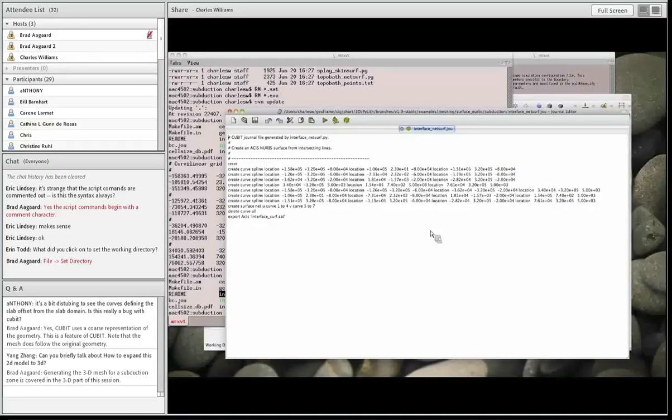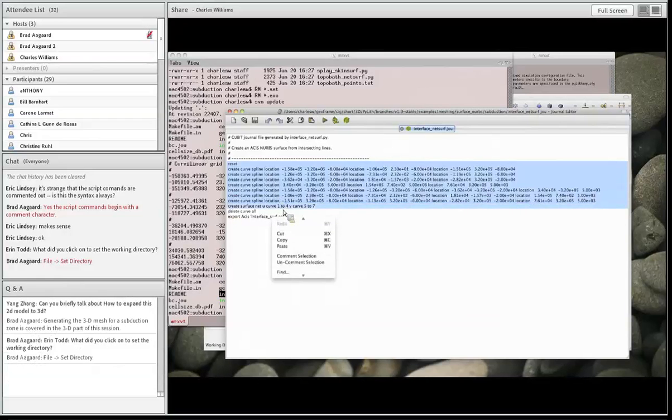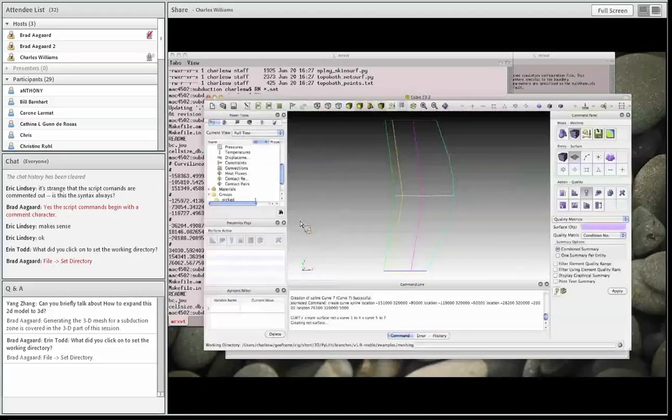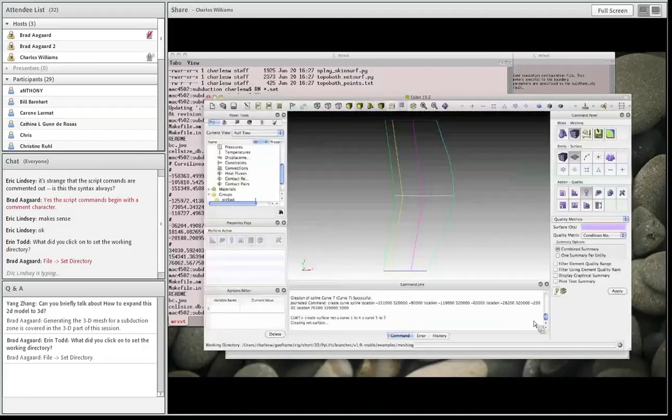Here, we're defining the contours. These first 4 lines are creating spline curves that make the contours. And then these last 3 are forming the profiles. So we'll just do all of that, and then we're going to create a net surface using those. I'll just show that part right here. Okay, this takes a little while to create the net surface, so if you have any questions while that's running.